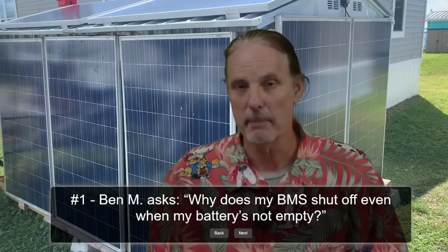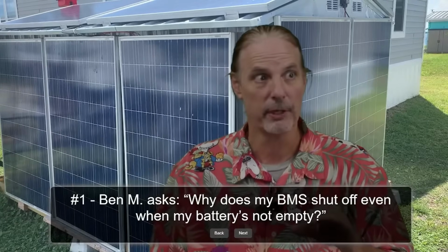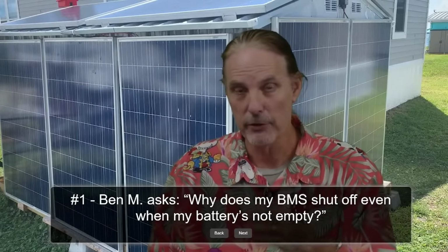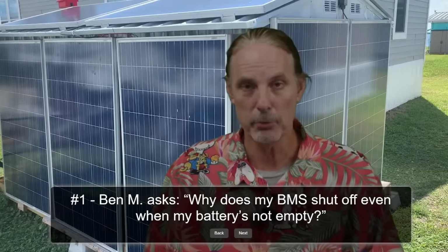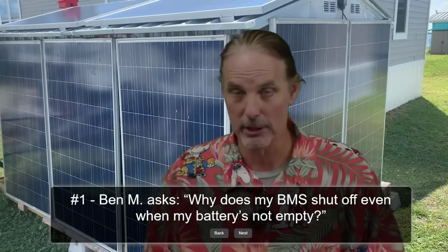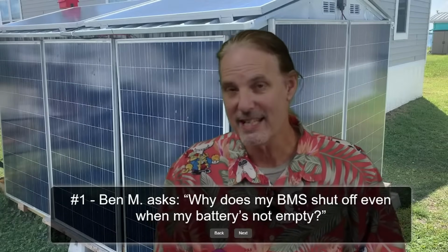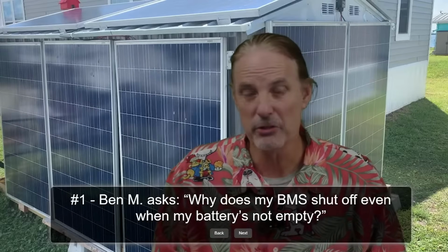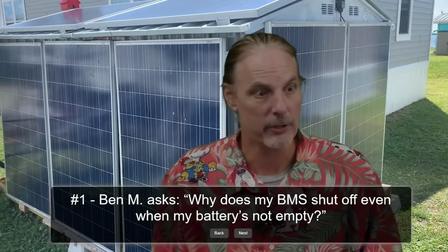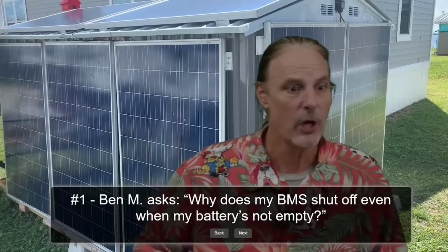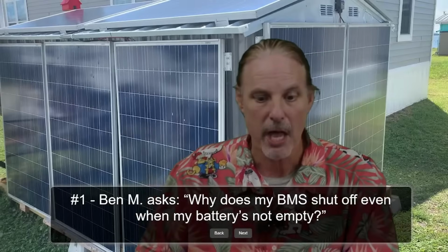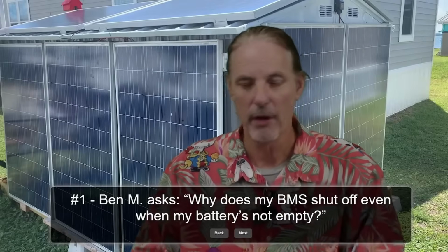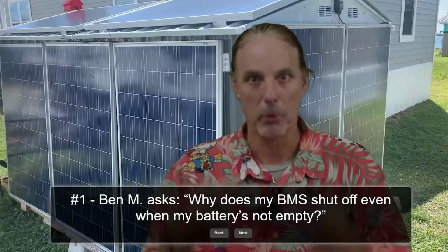Now, my JK BMS had exactly the opposite problem when it first started. It was completely whacked out in the other direction, and it would show that it had 10% left when actually it had about 40% left. After a calibration, it now shows about 5% more than it should, but that's after 2 months of running off grid and not being rebalanced. So that is why the BMS is shutting off before it is empty. This is the root of all of the BMS problems here.